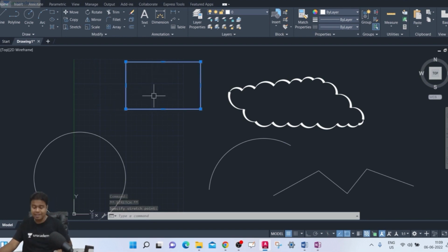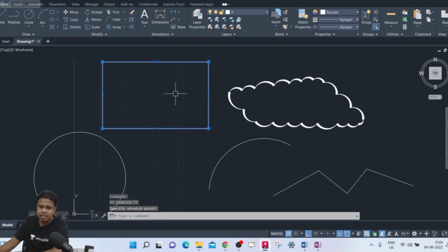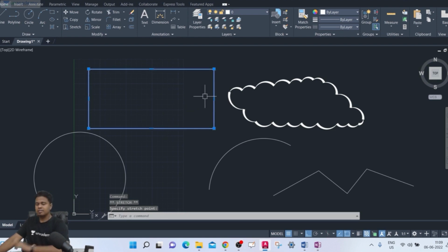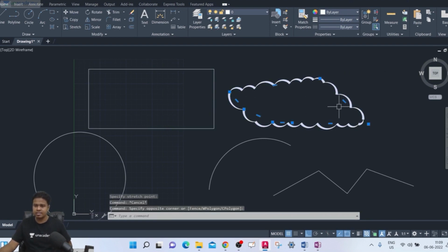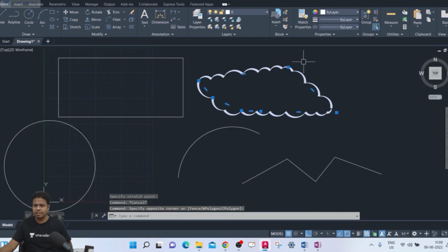Now I will show you one thing. Suppose you press ortho. See, as of now the ortho is on. Now you can move this either in the vertical direction or in the horizontal direction. Exactly. See here, left click onto this drag handle and stretch it in the horizontal or vertical direction. Okay, now you can use the stretch here as well. So we have different drag handles.